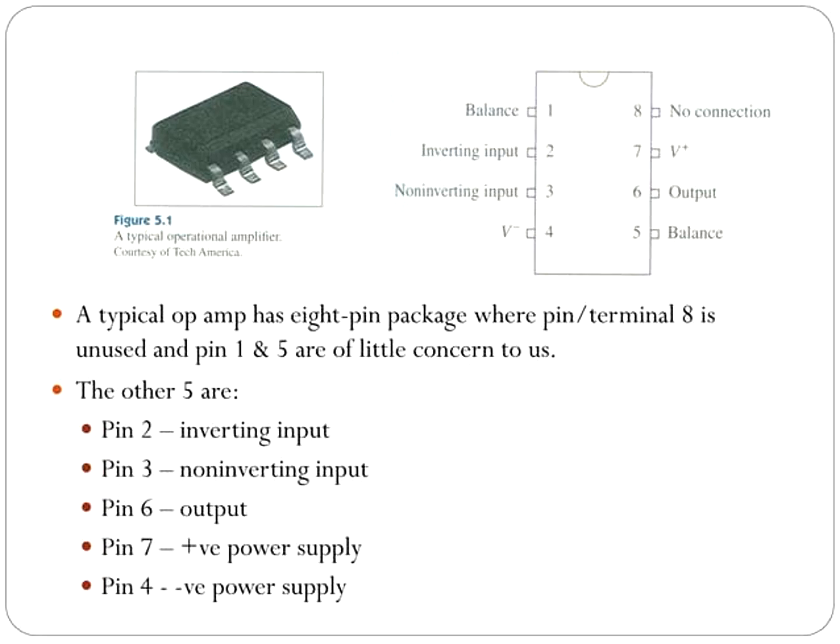pin 2, which is used as the inverting input, which means the positive of an input is given a 180-degree phase shift in the output, which means the positive of the input will appear as negative in the output. This is said to be the inverting input, and the non-inverting input is represented as pin 3. In this non-inverting input, what we give as an input, we will get as an output without